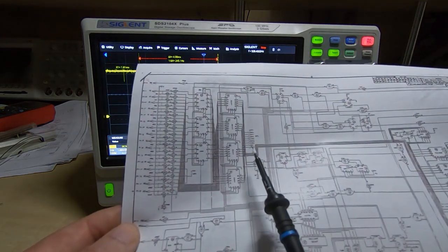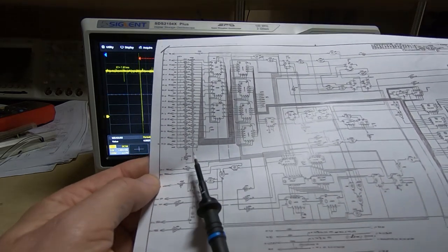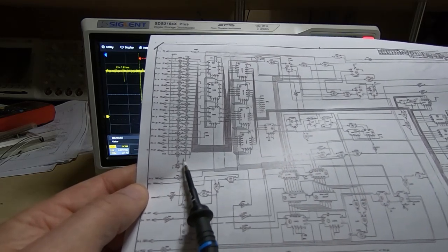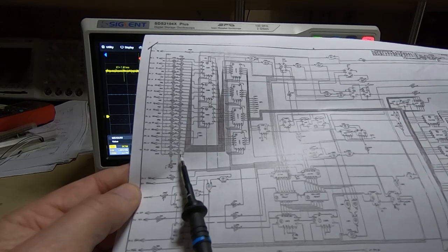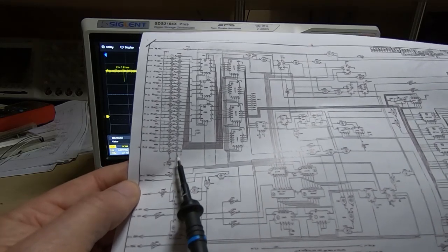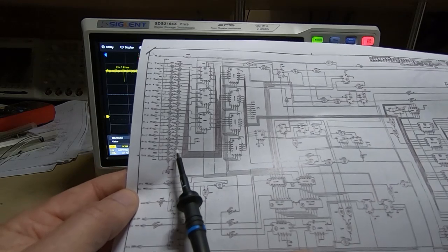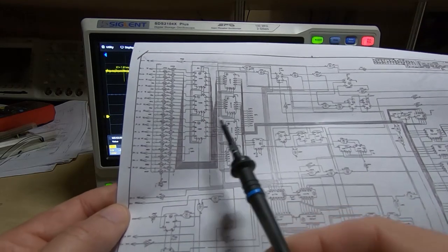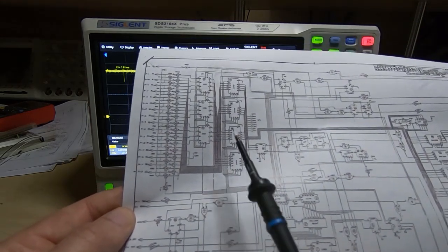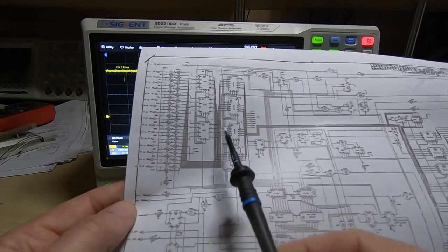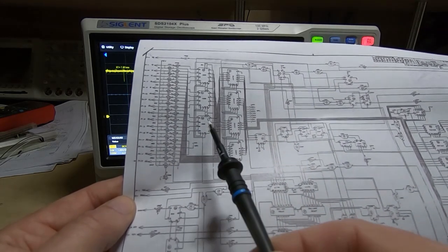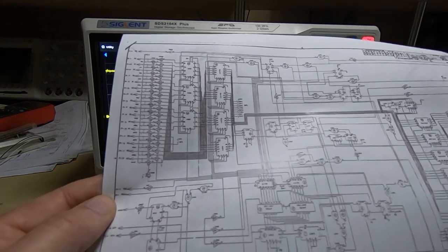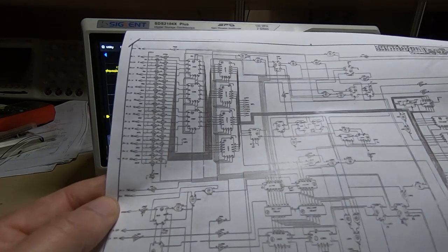But what we'll do instead of using the main system clock is we'll connect the clock on one of the pods to the control pin, the enable pin for the address out latch or buffer. And that means that we'll be able to capture the address values that are being sent out, and this should be incrementing from 0 up to the capacity of the monitor. So it should be going from 0 up to about 1,000 and then back to 0. But I suspect it's not doing that. But I'll attach the logic analyzer, we'll see what's going on and go from there.